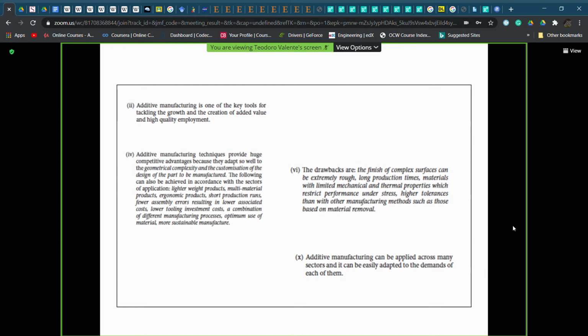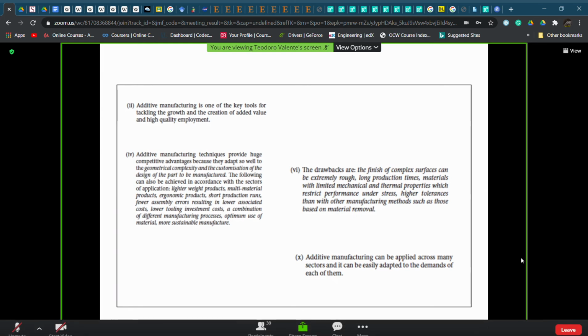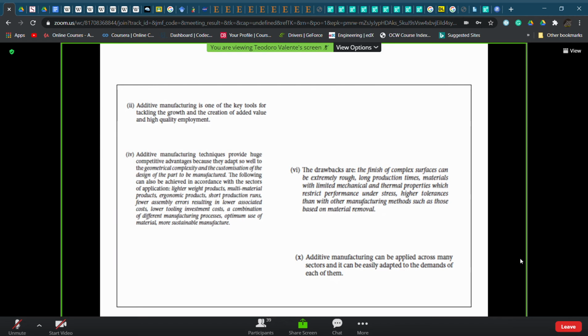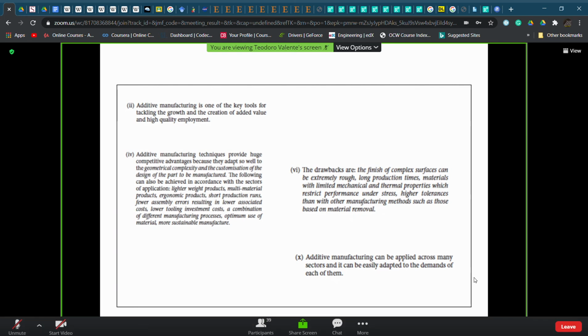Also, since we need to start from solid powders, then melt powders and then join powders, another thing, apart from the materials availability that I already mentioned, is the strict control of the porosity of the fabricated component, which can affect, as we said at the beginning today, in a negative way, the mechanical performance or mechanical properties, or if you want, the life of the fabricated component.